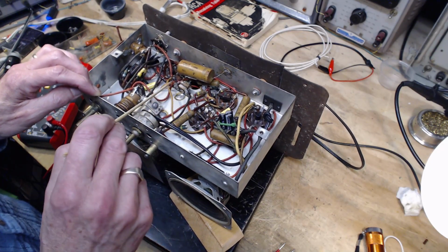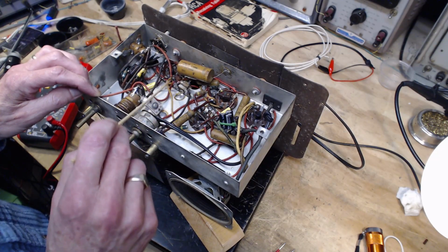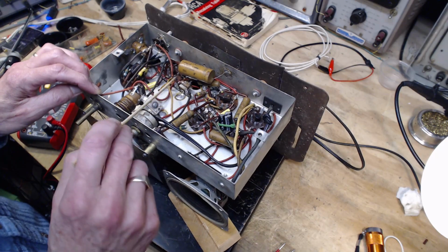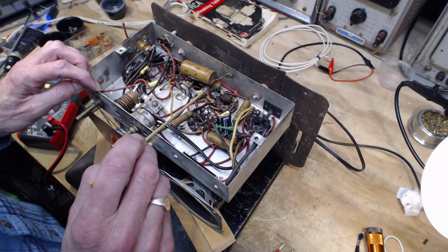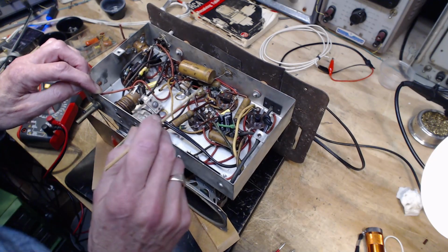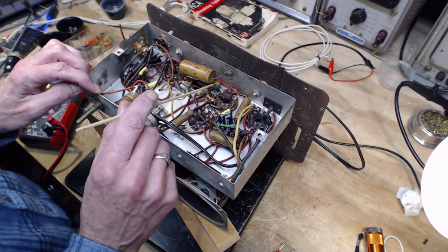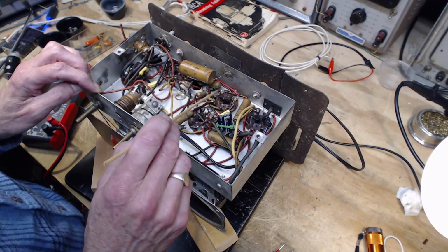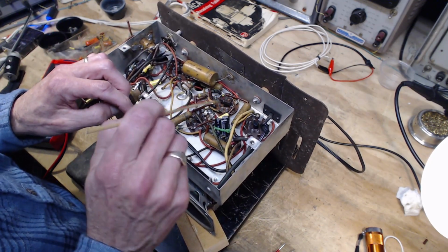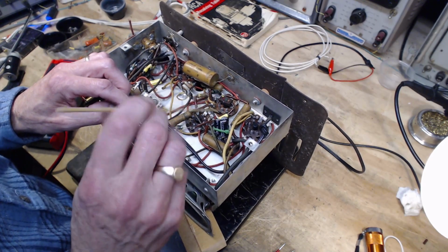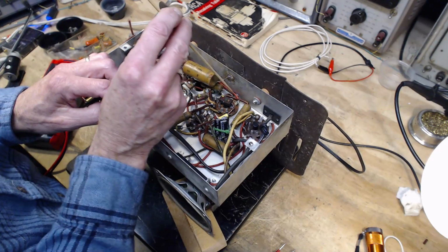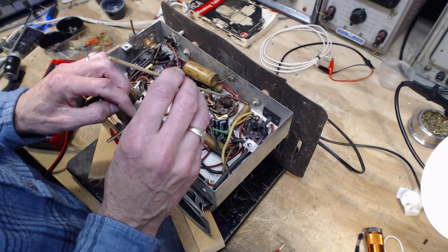So there's something quite obvious about this resistor sitting right here, mounted dead center and up on a terminal strip. And look, there is a capacitor connected to it, kind of hidden right there. One end of it is going to this terminal. This terminal is pin number 8 on this tube, and I can tell easily because pin number 1 is soldered to the chassis there. So that's 1. This has to be 8.